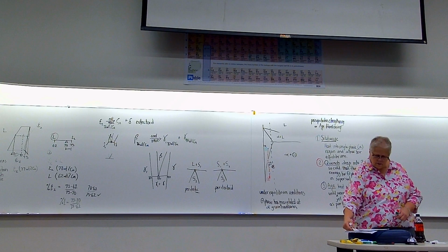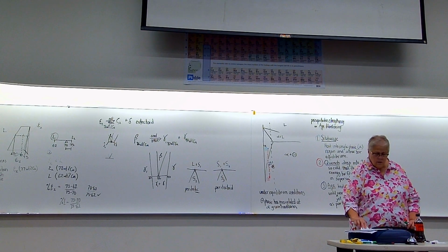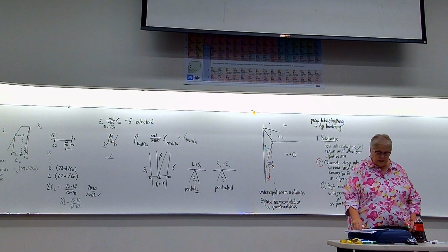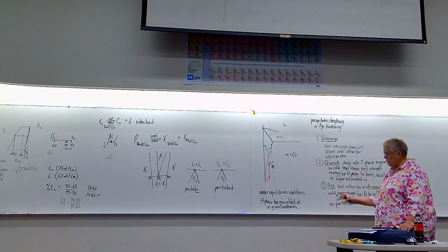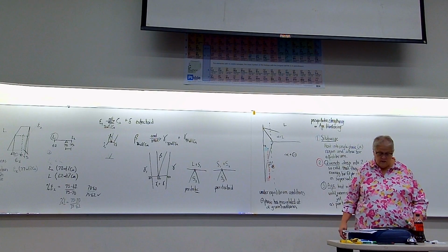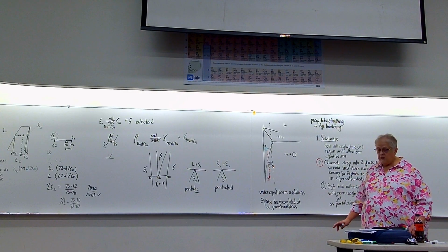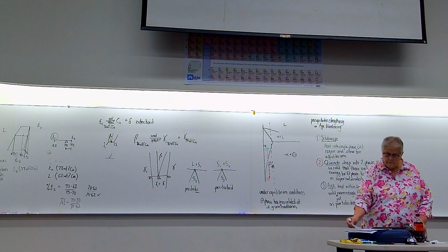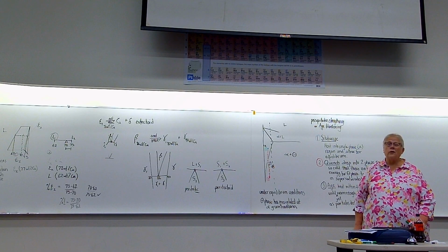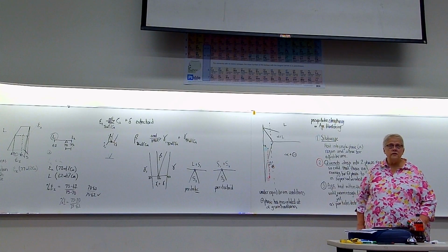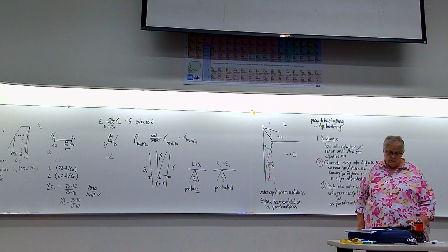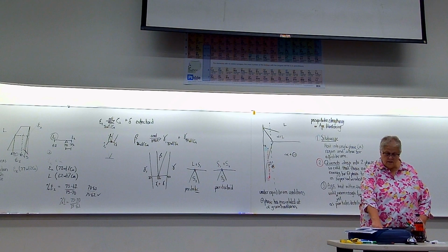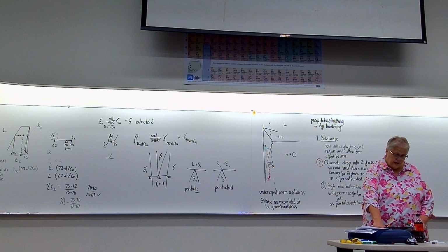All right, so you're given some temperature ranges for that solutionizing. It kind of depends on the composition, but somewhere between 450 and 550 roughly. So that's what, 450 plus 273, 673, 723. So that's about 723K on here to 823K.